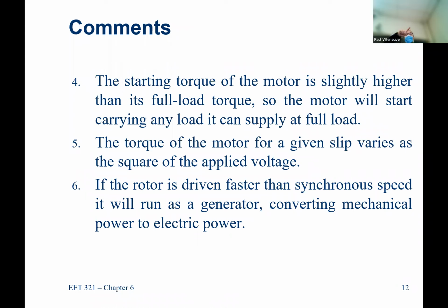As the wind speed picks up, it increases its output power until it reaches rated value, and then at some point it levels off. At that point, you start to feather the blade to shed some of the wind. It'll still continue to run because it's able to shed enough speed. But if the wind speed continues to get too high, you can't safely shed speed, so you have to apply a brake and force the turbine to shut down because you can't control the speed.